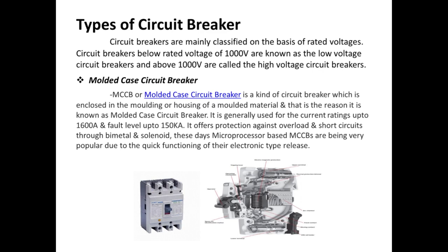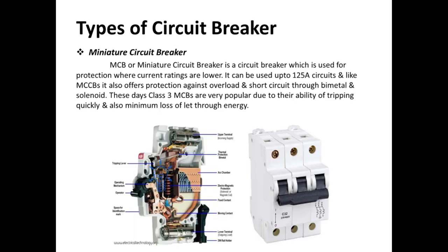It offers protection against overload and short circuits through bimetal and solenoid. These days, microprocessor-based MCCBs are becoming very popular due to the quick functioning of their electronic type release. So next is the miniature circuit breaker, or MCB.